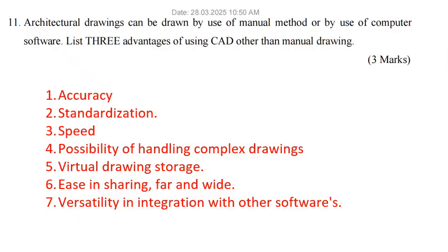ArchiCAD, as you draw the plan, you are also developing the height and the walls. And in ArchiCAD, we just use materials. So to place the roof is just simple. Just draw the roof position, and it will give you the roof automatically. Draw a line for the wall, and it will give you the wall. Then just place the windows where you want them, so it's quite easy and speedy.